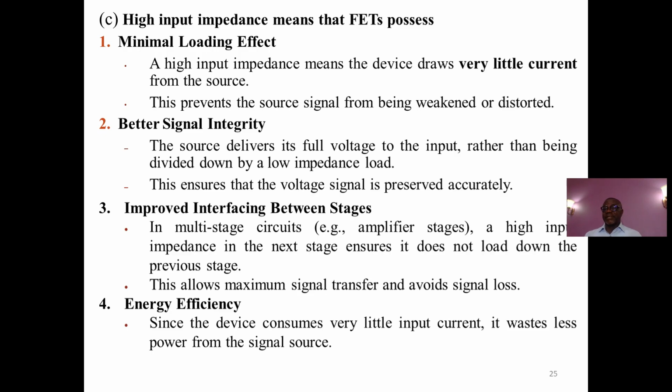What we are saying here is that if you have a voltmeter or a digital voltmeter that you are using to measure the voltage across a component, if that meter has very high input impedance, the impedance of that meter will not affect the voltage across the component you are measuring.